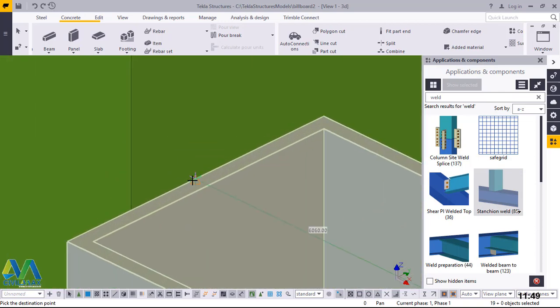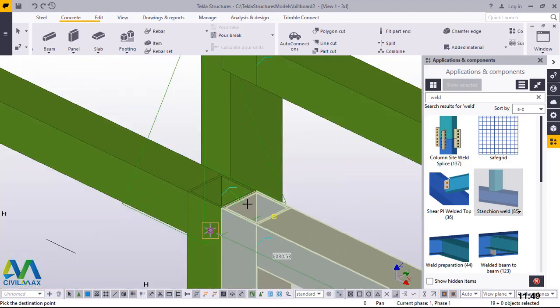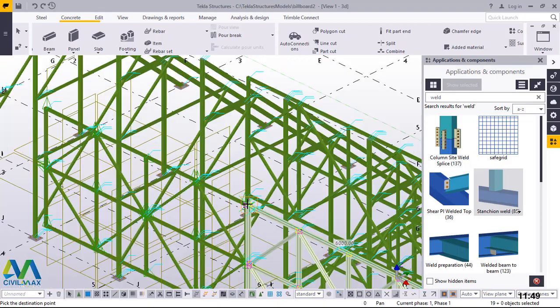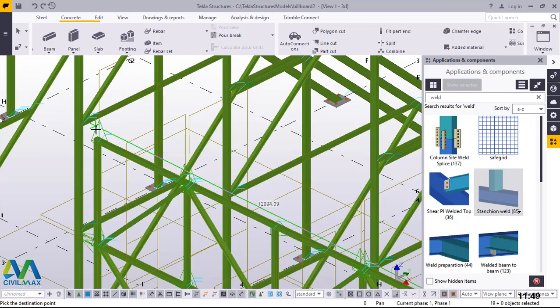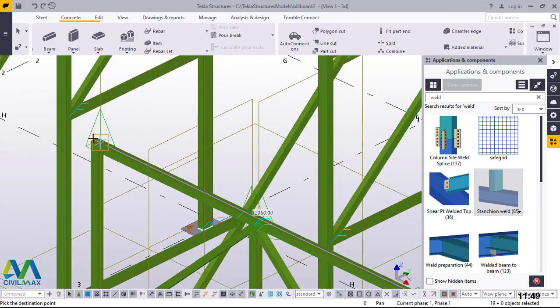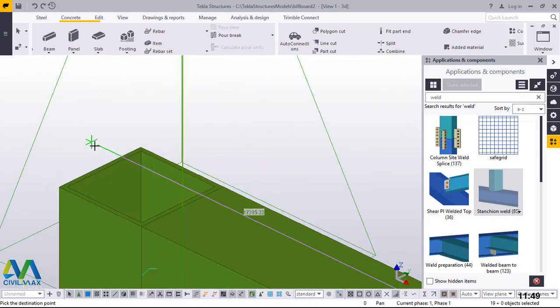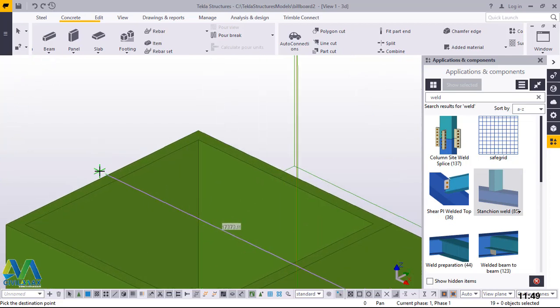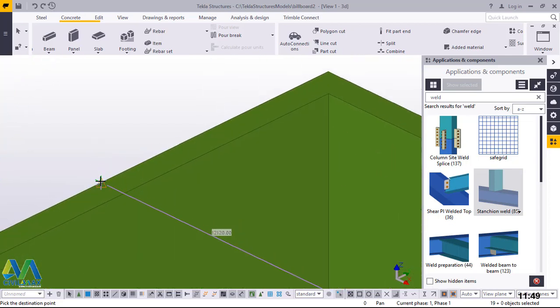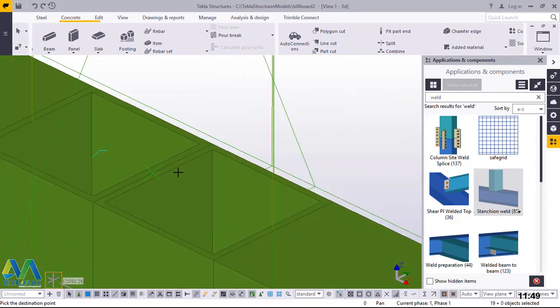The edges will be touching but not welded together. Once you've installed these frames to the supporting frames, you can decide to weld if the billboard will stay there for a longer period of time without the authorities asking you to remove it.